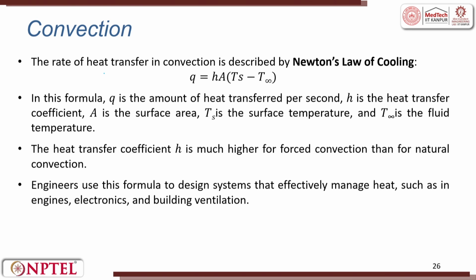So, the rate of heat transfer in convection is described by Newton's law of cooling, where Q is equal to h A (Ts minus T infinity), where Q is the amount of heat transfer per second, h is the heat transfer coefficient, A is the total area, Ts is the surface temperature, and T infinity is the fluid temperature.